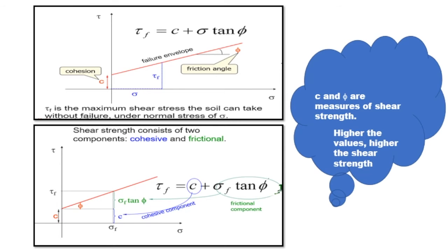As per the Mohr-Coulomb theory, the failure is essentially by shear, and shear stress at failure depends upon the normal stresses on the failure plane. It is a combination of the normal stress and the shear stress. The soil fails when the shear stress tau f on the failure plane at failure is a unique function of the normal stress acting upon the plane. This shear stress at failure depends upon the cohesion, effective stress, and the angle of internal friction.